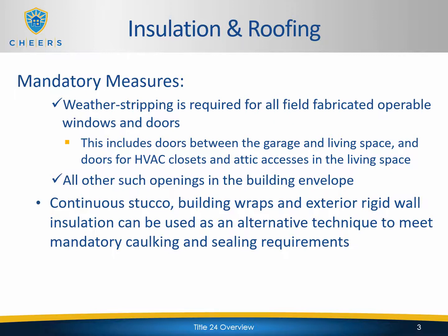Weather stripping is required for all field fabricated operable windows and doors. This does include doors between the garage and living space, and doors for HVAC closets and attic accesses in the living space. All other such openings in the building envelope.